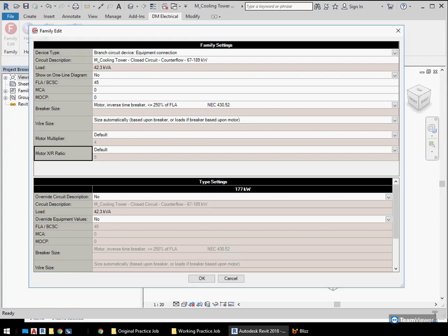The recommendation, kind of the default, if you look at the IEEE manuals, is 4. The load is going to be 4 times the motor. If you happen to have a different value based upon a specific motor, you can override that. But if you don't know and you're just doing a standard project, a commercial building, 4 is going to get you what you need.